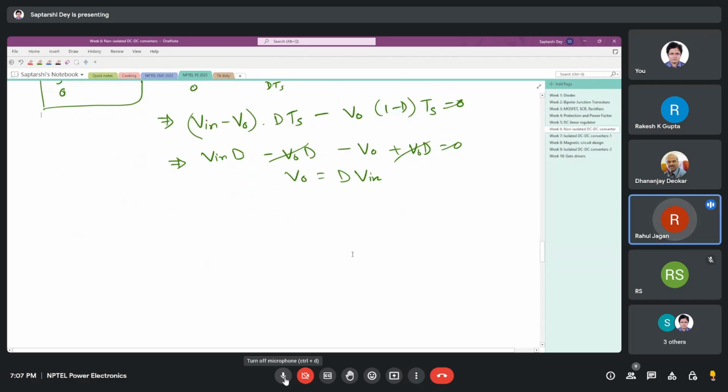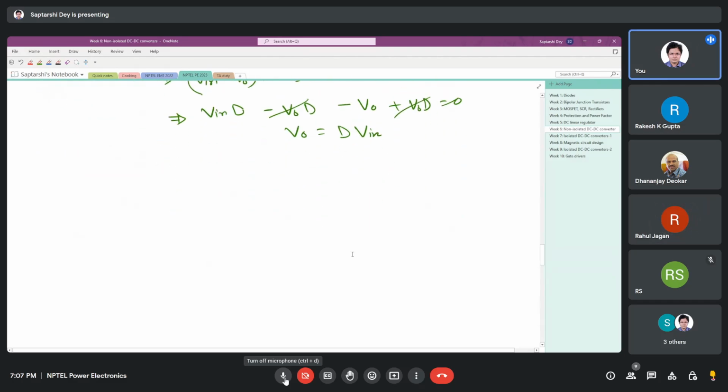So what happens in the dynamic condition then? No, he's talking about discontinuous conduction. No, I'm asking regarding the dynamic condition of the inductor. Dynamic condition means sometimes it is DCM, sometimes it is CCM. No, it cannot be sometimes DCM, sometimes CCM. It depends on the load, but the controller will take corrective action for both the states. If you have a controller, then yes.